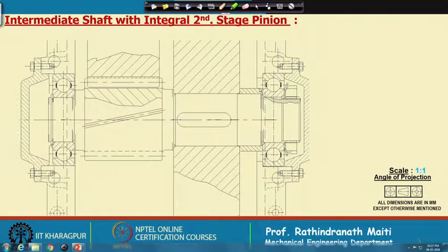I shall mention later of course, but here one interesting part is that while we are putting the gear on the shaft, first of all it should be tight fit. It might be light drive fit, by no means it should be running fit or loose fit. And then if we think of this spacer which is connecting the gear side with the inner race, to confirm that these will touch both the gear and the inner race without any interference anywhere, what we do, the